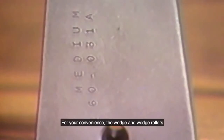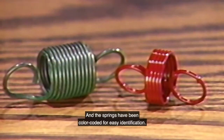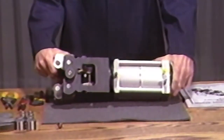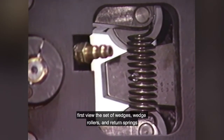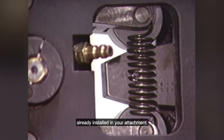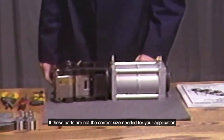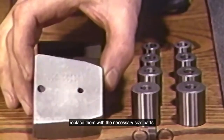For your convenience, the wedges and wedge rollers have been stamped with part numbers and sizes, and the springs have been color-coded for easy identification. To select the proper combination, first view the set of wedges, wedge rollers, and return springs already installed in your attachment. If these parts are not the correct size needed for your application, replace them with the necessary size parts.